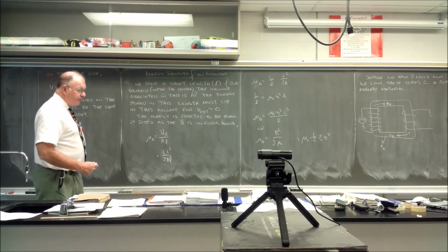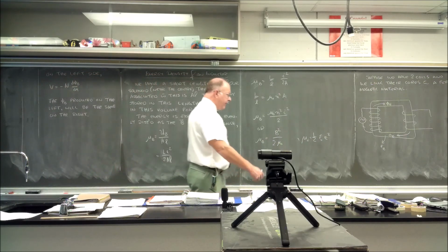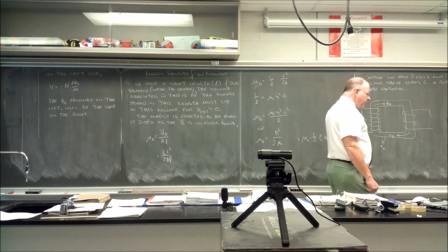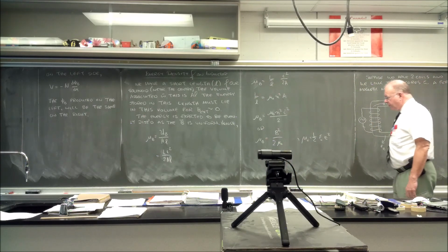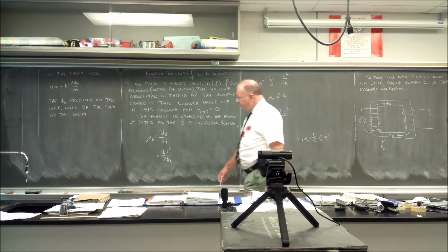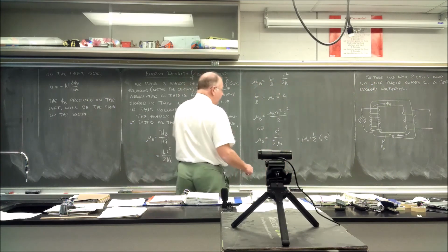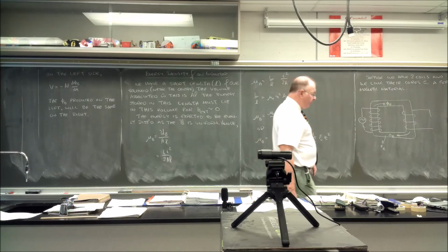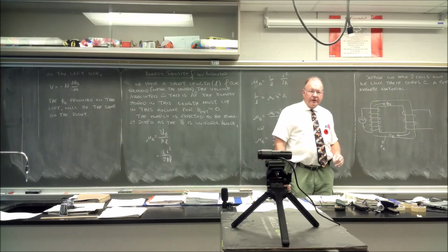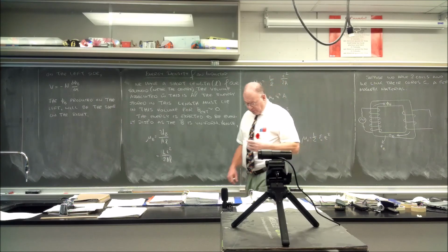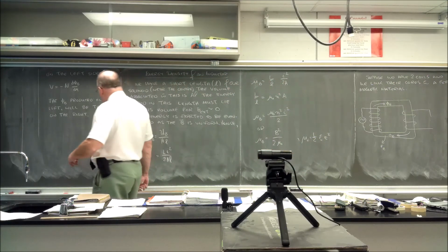Okay, they're linked because of the iron core. You can do it with air, it just doesn't work as well. So having the cores done like this works quite nicely. And you could even use that pipe version I showed you earlier, it would work the same way. It doesn't have to be complete, it's just more efficient because the field will continue all the way around.